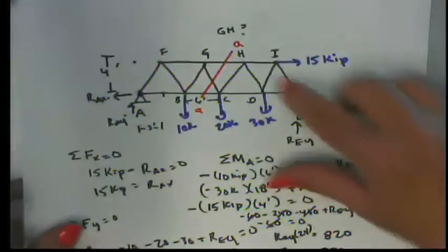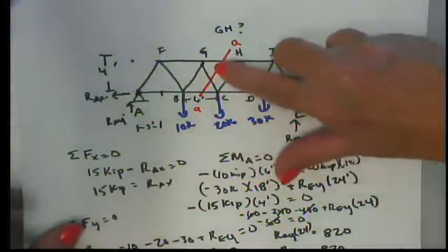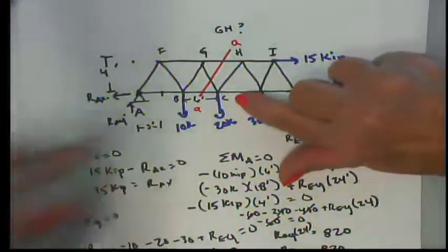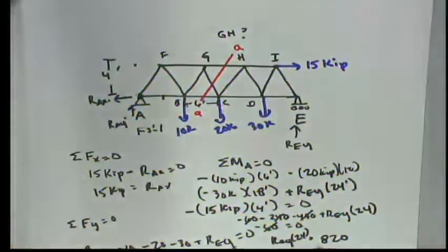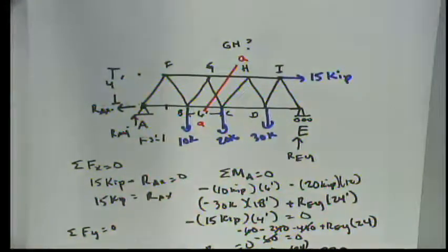But if you did that, you'd have to swing it over this way so that your unknowns would be this, this, and this. Do they have to be angled? It can't be straight. Well, what I'm saying is, if you cut right through C, what does that mean? In other words, this force has to either be on the truss or not on the truss. And if you cut right through it, you don't really know. Yeah, good question though.